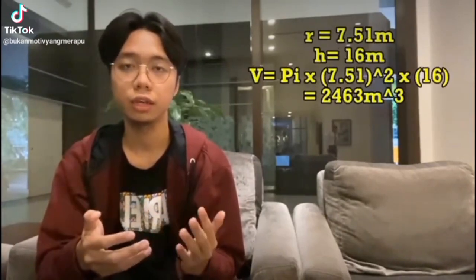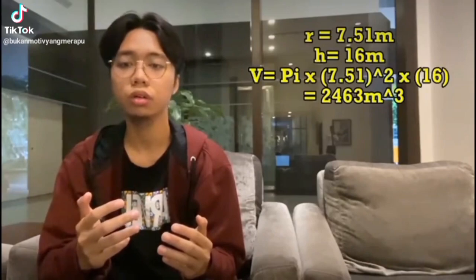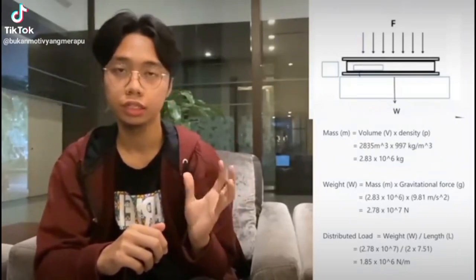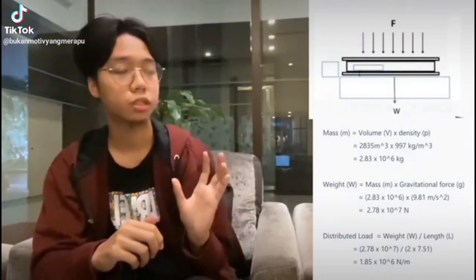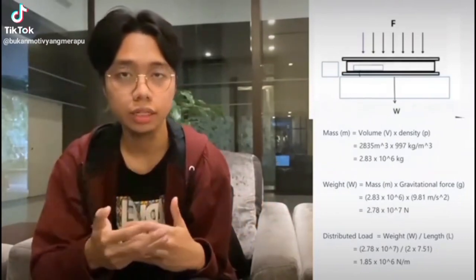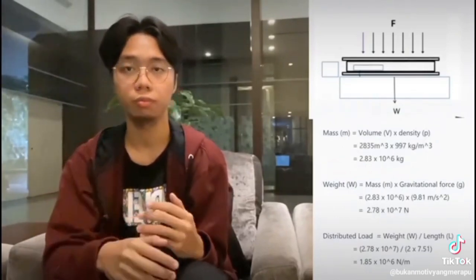So the height is still the same, 16 meters, but the radius is 7.51 meters. So we can get all the information on this diagram by using the density formula. Then we can obtain the mass, and the mass we multiply with the gravitational acceleration, and then we can gain weight. After that, we divide the weight by the length of the cylindrical water tank, then we obtain the distributed load.